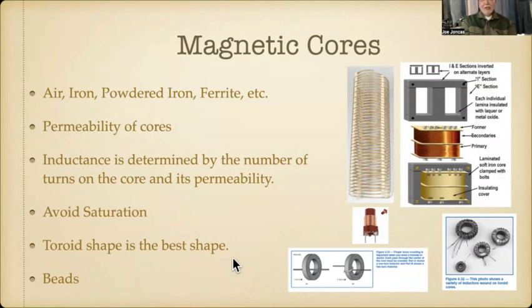And if you ever see them, you might have a transistor soldered into a soldering board, and one of the leads will have a little tiny bead on it. What that does is keep that transistor from going into self-oscillation. And if you see one, you'll know what it's for. If you're having oscillating problems in something you're trying to build, that's a good thing to try.